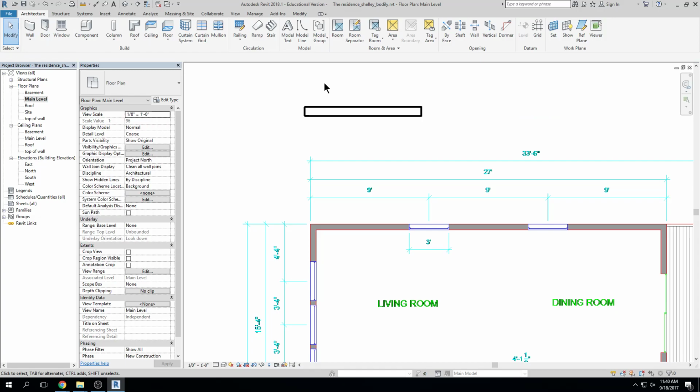The way that I go about drafting is usually when I have a group of tasks that are similar, I complete them all at the same time, right? If I'm starting a new file, I bring in any type of title block or other families I need, I set up sheets. I do all my setup tasks first, and I get ready to print so that if I have a client stop in, I can print. If I need to create 5 or 6 wall types, I don't create one and then draw with it. I usually create all of them at the same time.